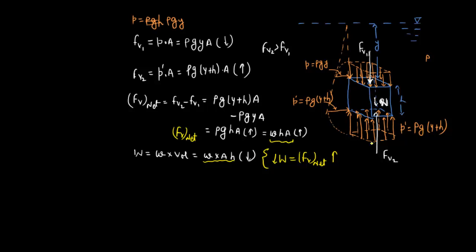But the vertical force will still be equal to FV net, because this is due to the surrounding fluid around this empty space. As there is no balancing force for FV net, because W is 0, the net vertical force is acting in upward direction. So this void, or empty space, will start to move in upward direction.